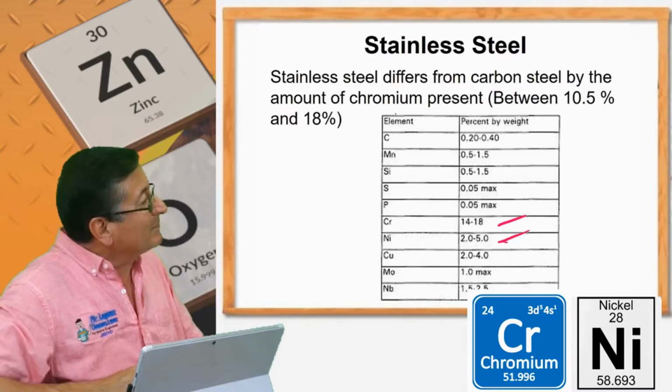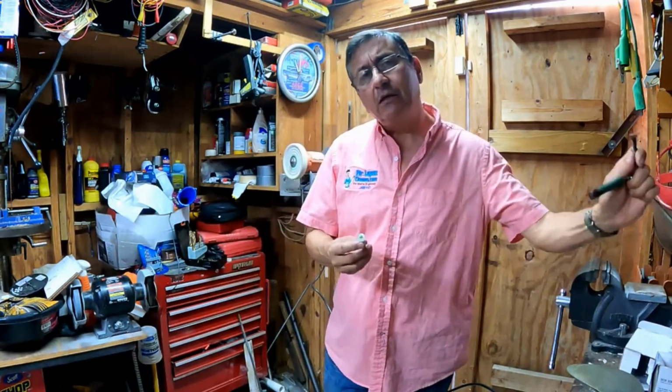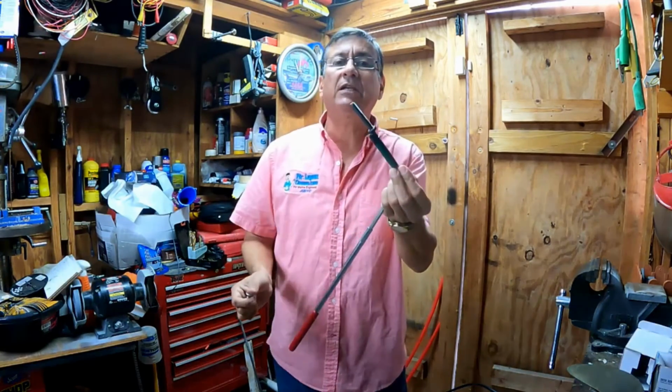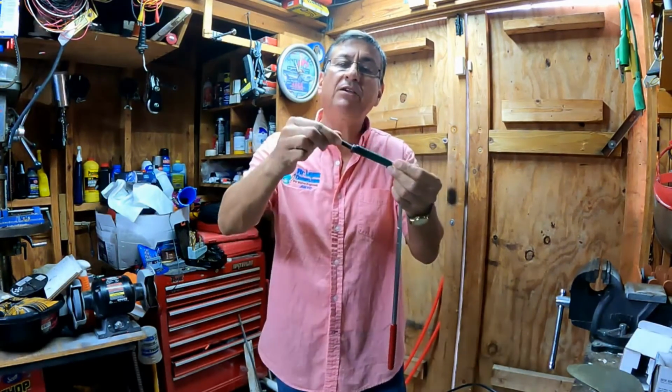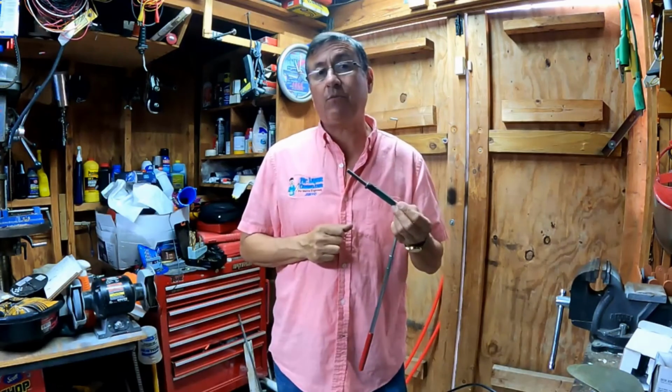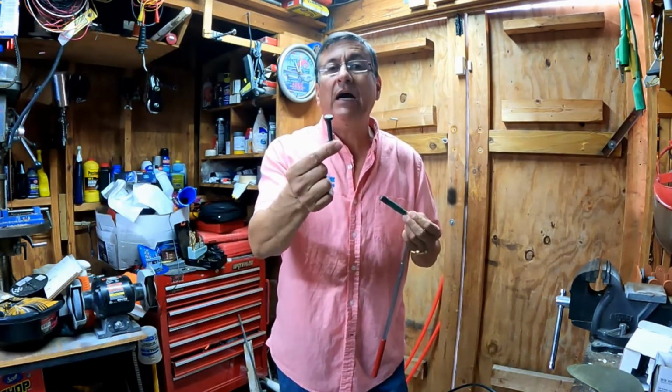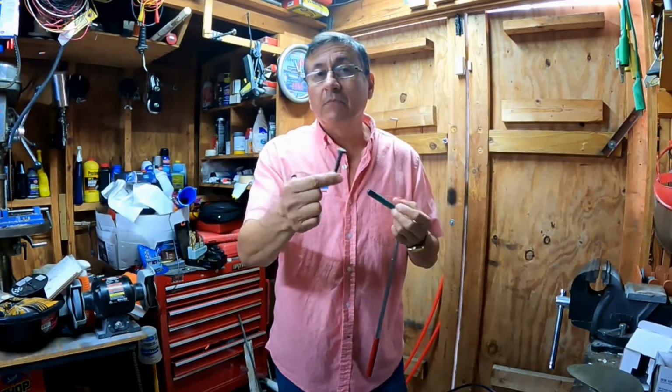Check this video. Like I explained in previous episodes, you can check if a steel is marine grade basically with the magnet. For example, this is a plain steel, it's magnetic. It's a plain steel with high content of carbon. This steel is highly corrosive and is magnetic.